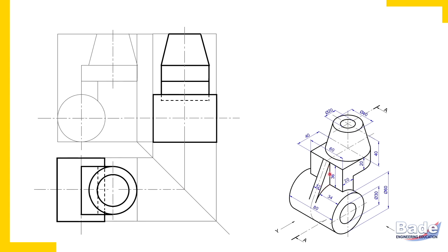Its largest surface, watch here, appears in the front view, and in the remaining two views it should appear as a strip. So its largest surface we can easily create because this plate is in contact with the curved surface of the cylinder and that vertical plate, this vertical plate. Okay, so let's draw it here. Before that, watch here, this is a hidden line. Remember these two edges where these two plates meet here, there is no sharp edge. So I have erased the dark line here and I have drawn a dotted line.